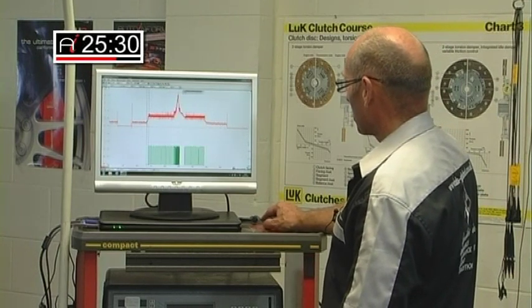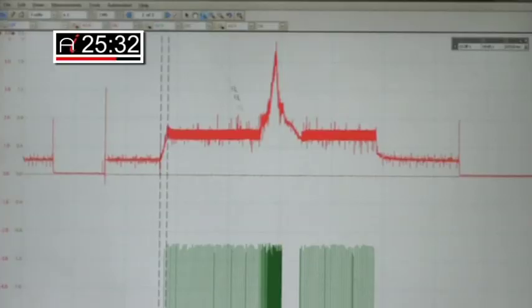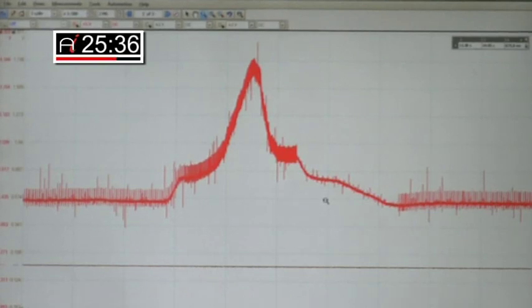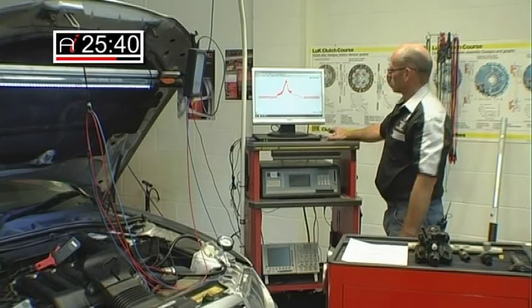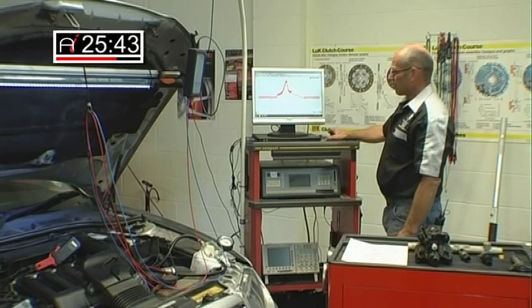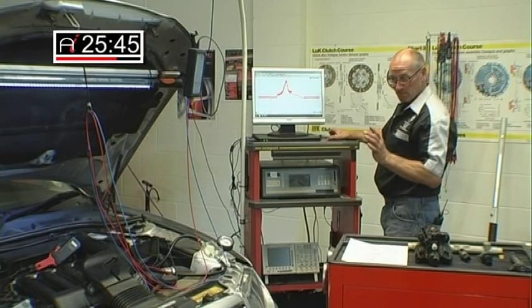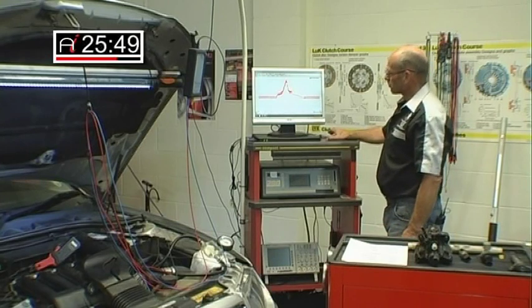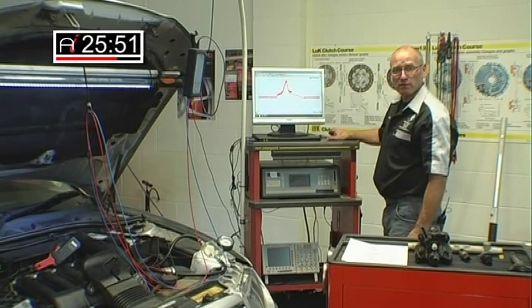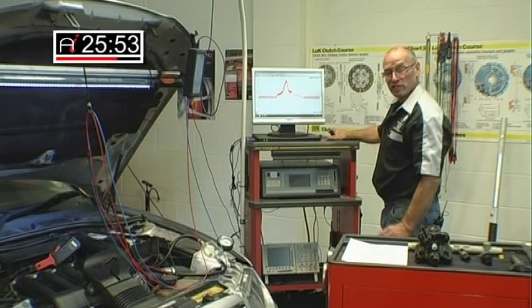So the next part of this assessment is to look at this part of the test. I want to look at the maximum value voltage achieved. This can vary from system to system, but this particular variation, Bosch CP1 DDE4, should create in excess of 4 volts peak voltage when the engine is revved up statically.